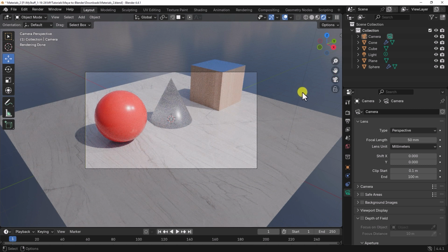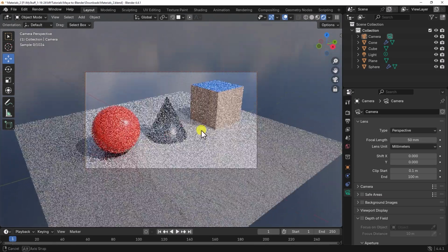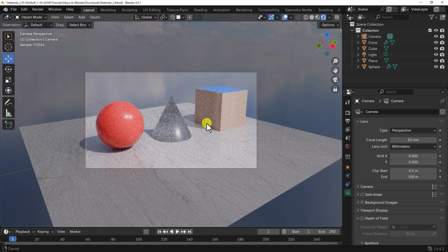Once you are in this mode, notice the little icon below the camera icon has changed from an orthographic icon to a lock. Click on the lock. Now, when we orbit, pan or zoom, we are locked to the camera view, allowing us to frame our scene using familiar tools. This looks good to me. I can now uncheck the lock and return to my scene.